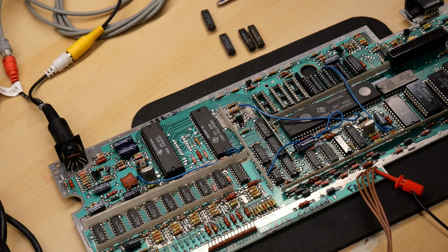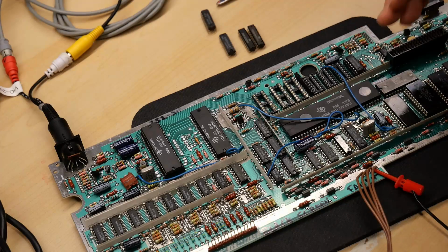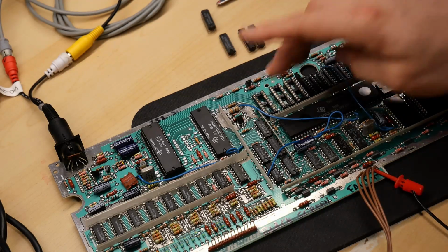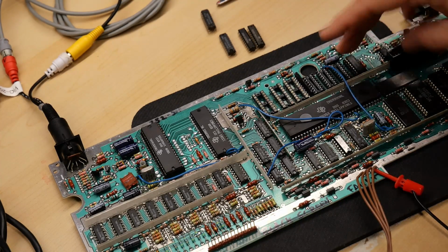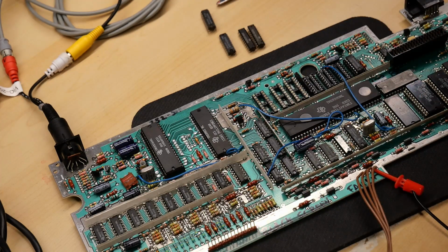Okay, one thing that's interesting is when you turn on the computer now, the sound starts changing. Listen. It's like it's phasing a little bit. And that's probably because the sound chip is on the other side of these chips. So I think that's happening because with these chips removed, this is now isolated. The sound chip is isolated, and it's just seeing random junk on the data bus, and it's, of course, causing the sound to change. But that's fine.